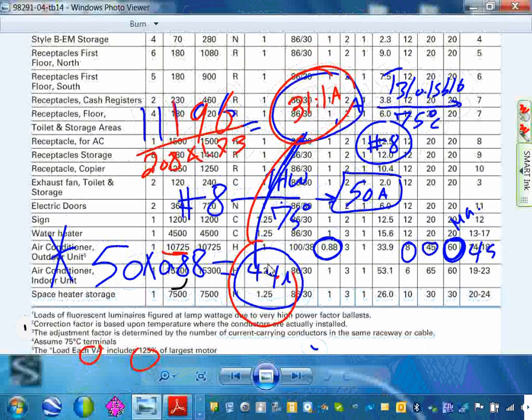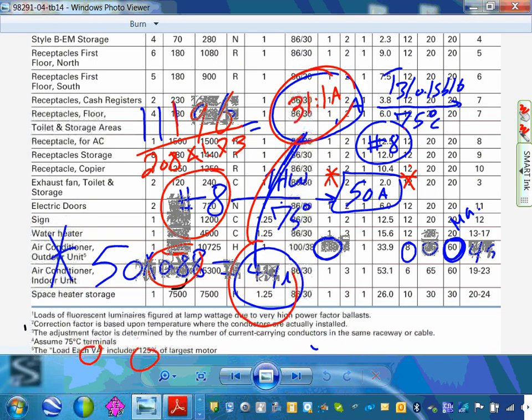Then, after you find the conductor, and I emphasize the word then, you take your conductor, and under whichever column the conductor is rated for, like THW, find the maximum current that this conductor can carry, right? In our case, 50. Then you multiply it by the temperature and derating factor, okay? And that will come up with 44.